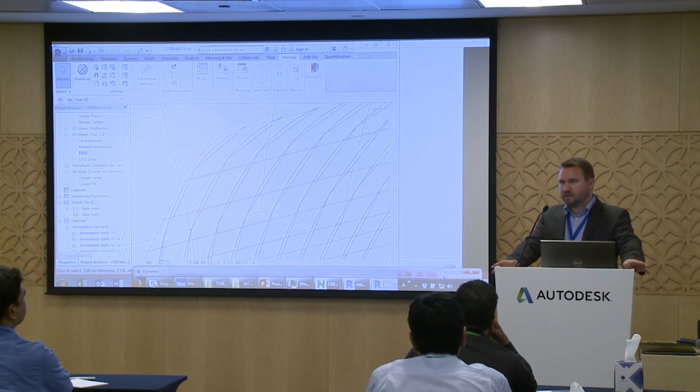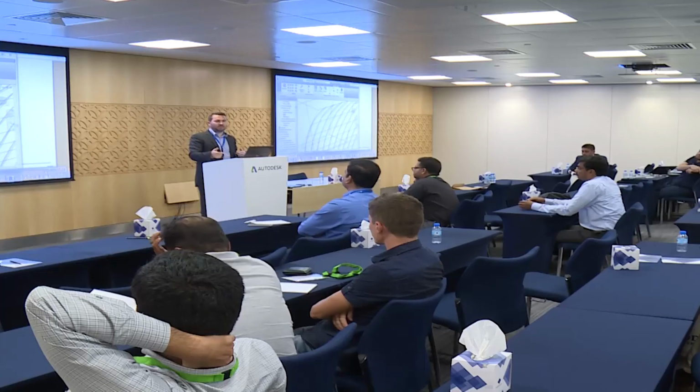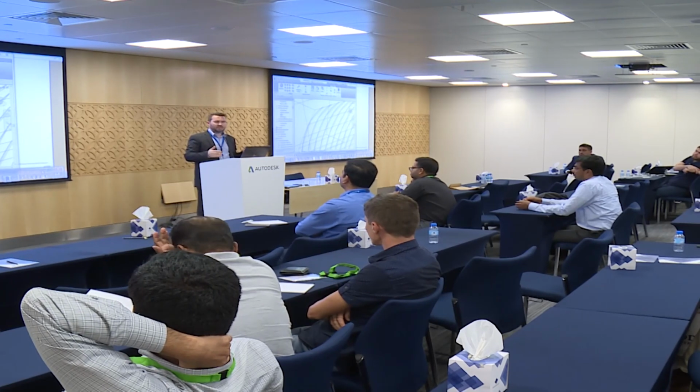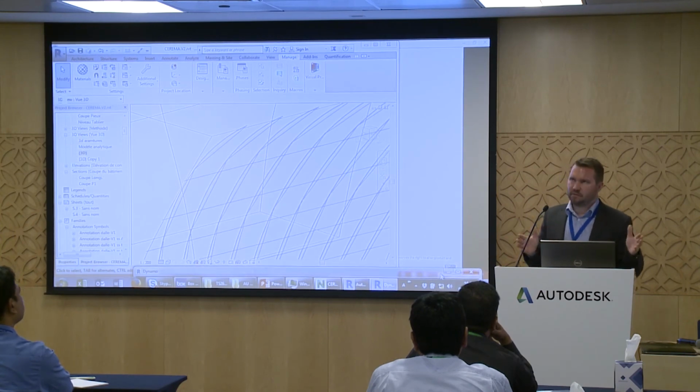You should not split when you want to tag. If you are in your file, and you see the element, but it's in the other file, you won't be able to tag. So sometimes what is strange, and what I don't say, is to split structure and architecture. In spirit it's nice, but for example, the wall and the opening belong to both, and so there are different solutions for different companies.